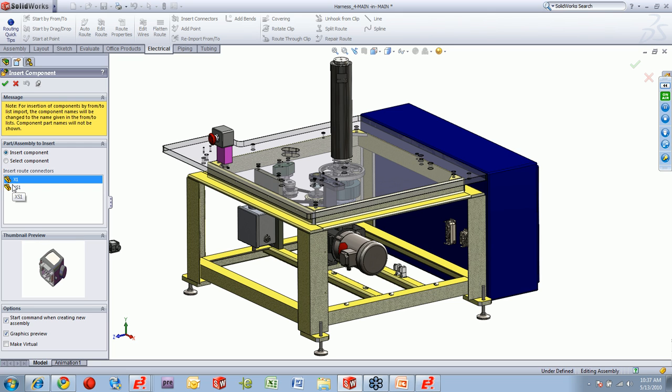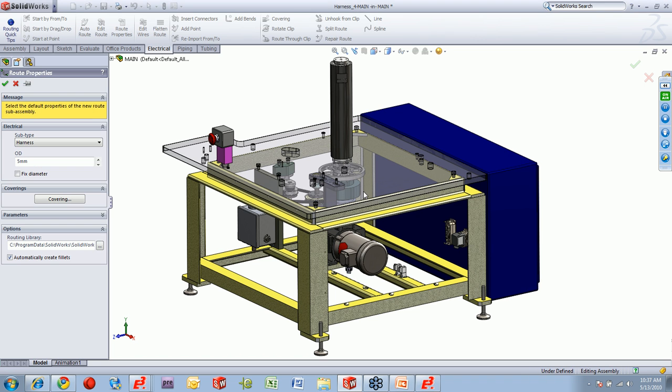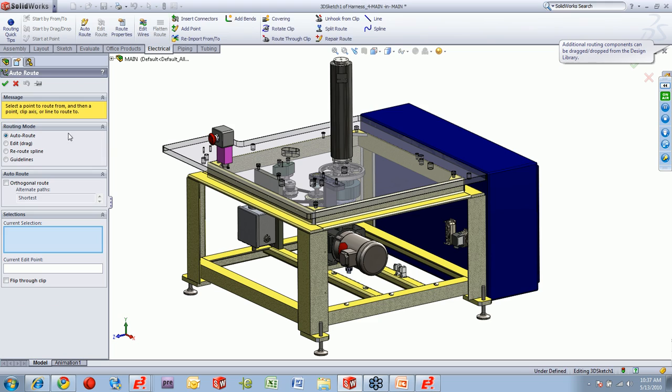So what E3.WireWorks does with its library is it cross-references what your components are with SolidWorks models. And then it will automatically call them up if they're in your library with that SolidWorks name. So here we have our first connector. We'll attach that to the panel. We'll do our second connector. We're utilizing smart mates here as well to ensure that things snap together appropriately.